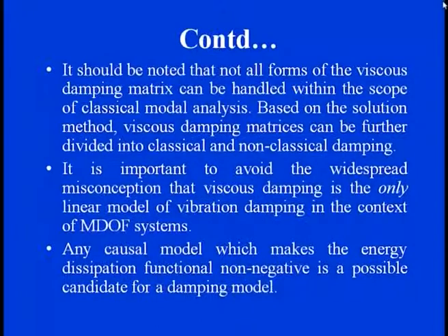So, that is why it is important to avoid the widespread misconception that viscous damping is the only linear model of vibration damping in the context of multi-degree of freedom systems. Any causal model which makes the energy dissipation function non-negative is a possible feature of our damping model. So, again you see we need to redefine those things for that.